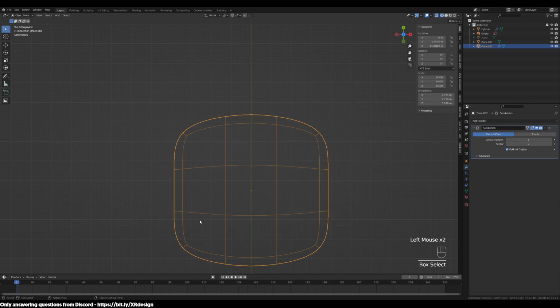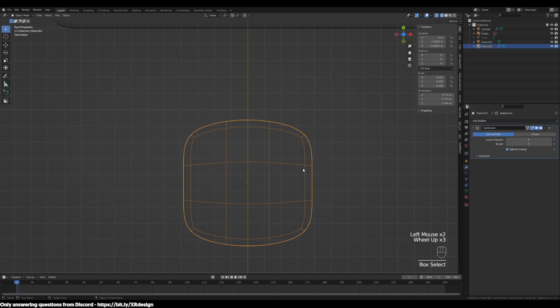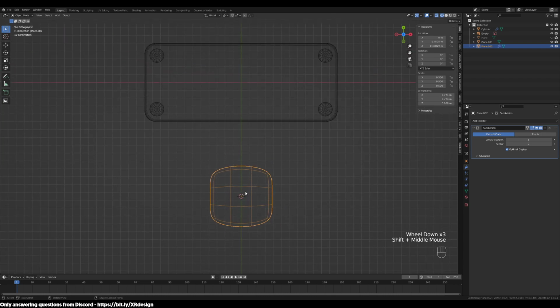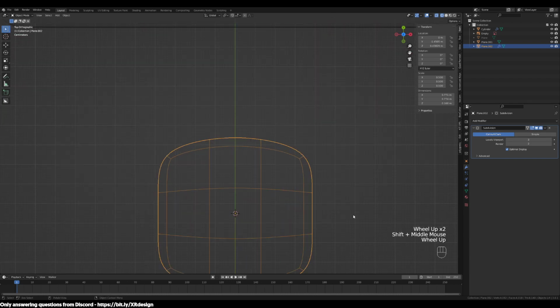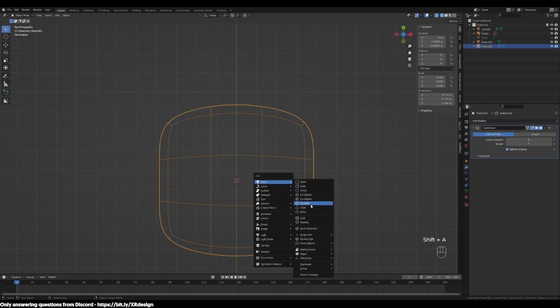So with this chair selected, if you haven't deleted that cylinder, delete it and select the chair. We're going to hit Shift S, and this will bring up options to tweak either the location of your selected object or the 3D cursor. So for now, let's do cursor to selected on the bottom, and that 3D cursor snaps to the origin point of your selected object. Okay, and then with that done, let's do Shift A, add a cylinder.